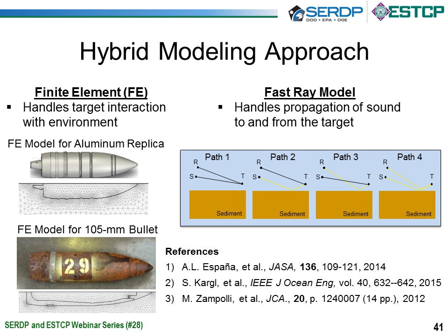One of the ways that Steve and Aubrey have developed to do this very efficiently is to begin with a finite element model in the free field. By the free field, that means they simulate a scatterer like this bullet here in an infinite vacuum or in an infinite volume of water. So it's the only scatterer present. And then they look at the acoustic response as a function of arbitrary orientation. So they have a complete response of the object for any orientation in this free field environment.